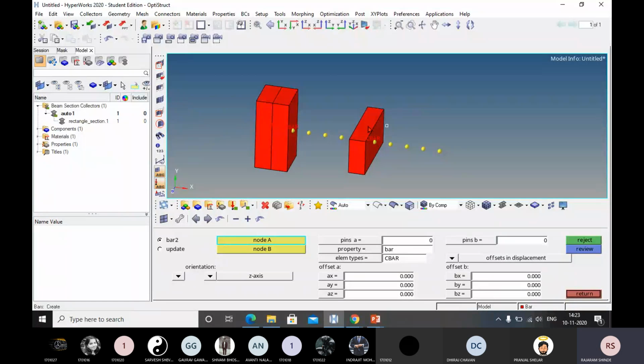That is distance of extreme fiber from the neutral axis. It will be different for this section and for this section. So you will not get the same stresses. Okay, your equation is M by I into y. Y distance is different for this section and this section. So you will not get the same stresses. Have you got it? So orientation is important.